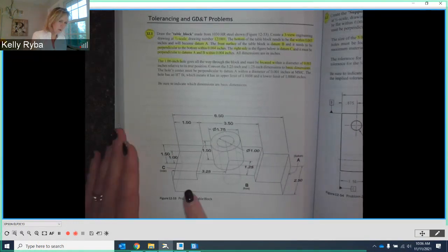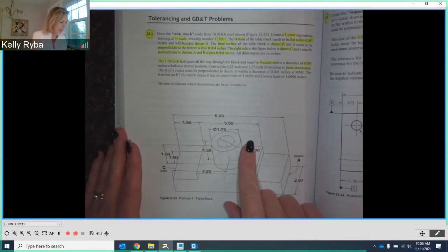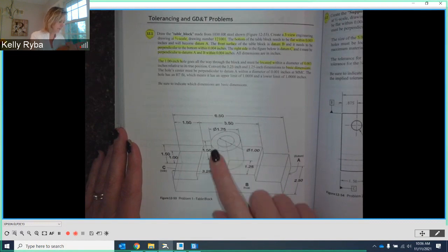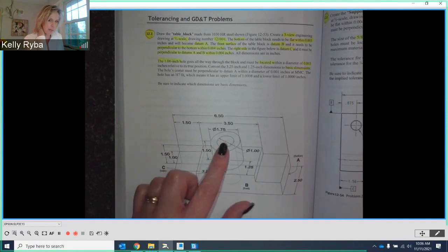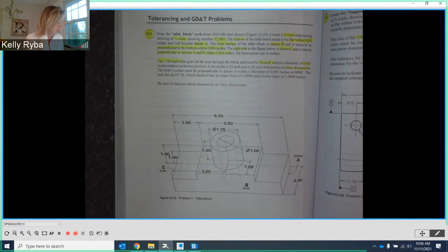I used a front view, okay, and extruded through this way, and then I added kind of this, the cylinder on the top, and then put my hole all the way through. I did not use the hole wizard. Okay, I actually extruded and removed material to put this hole all the way through all surfaces. I just find that it works better. I'm not crazy about the hole wizard as they do it.